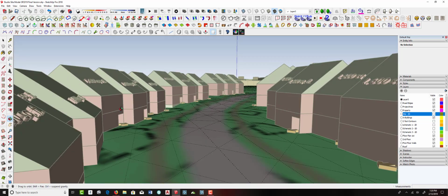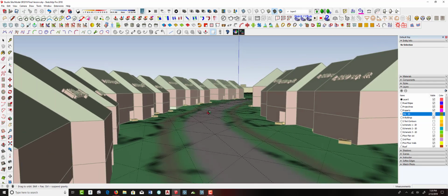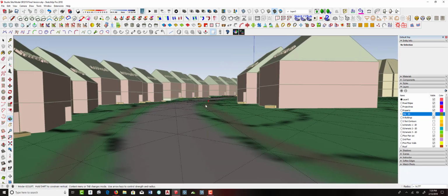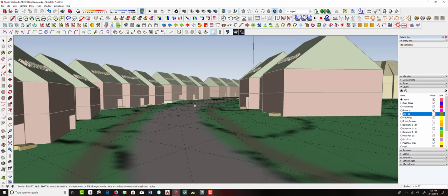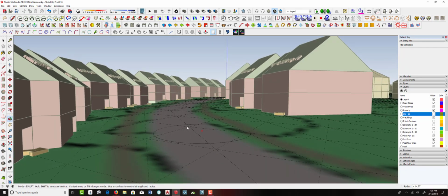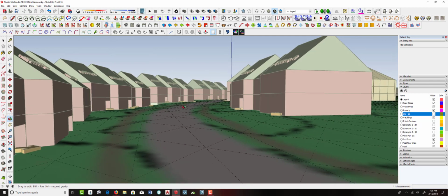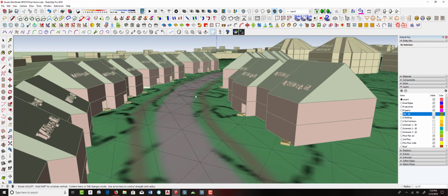And I can also go into the roadway and say, all right, well, let's right click and do sculpt. Maybe I'll adjust the influence a bit. I'm going to pull this up in here, smooth this out a little bit. Just look at the roadway, how that kind of comes down between the units. Maybe here I need to go down a little bit. So you're basically doing sculptural grading. You're just looking at this and making visual judgments. We can go back and look at the contours later, but it actually gives you a pretty nice way to quickly adjust that. Then I can go back to sculpt, adjust this up. Sorry, I want to go back to smooth and smooth this off.